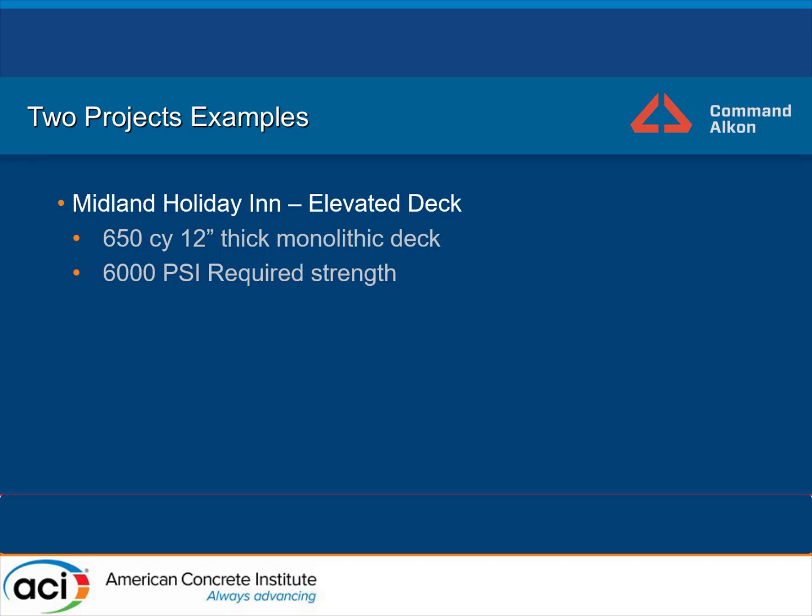And C, we have to have a low water cement ratio, make sure the drivers don't add additional water, and make certain that the contractor doesn't add water. The super's going in on right, and he's insisting we pour when it's 23 degrees. I'm also very concerned about the concrete temperature for this particular pour because I didn't have a lot of confidence in this contractor following ACI cold weather concreting guidelines. But I know if I got at least 50 degrees temperature, I would be okay.